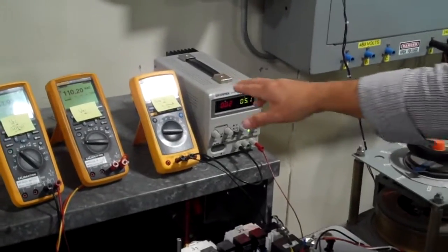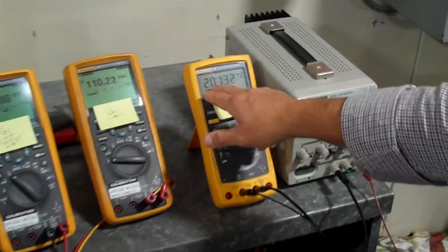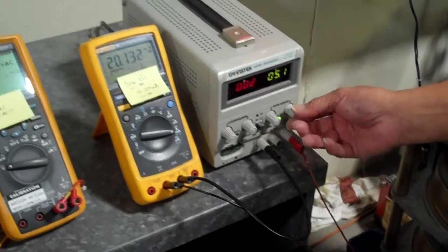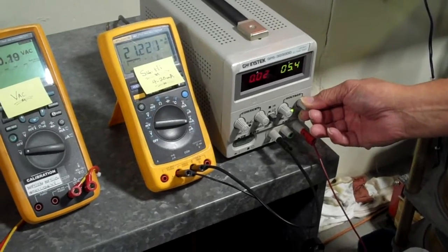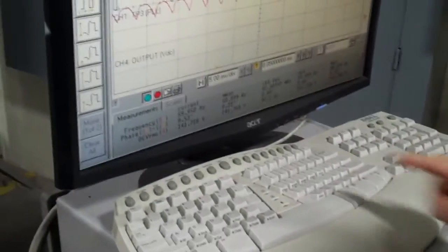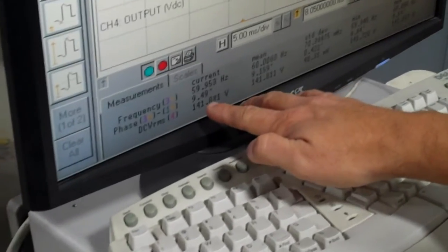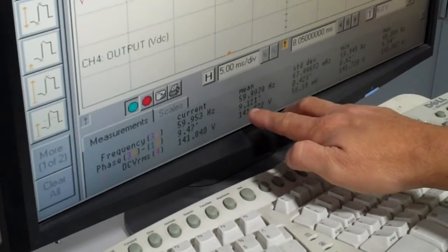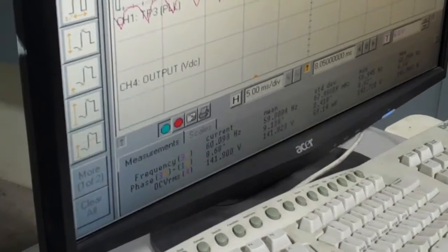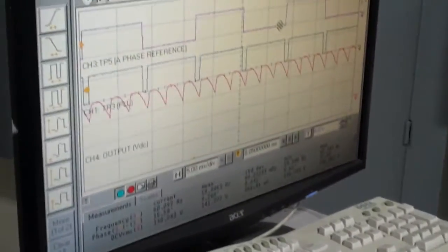So Tony, if you can slowly, by the way, and the corresponding voltage for 20 milliamps is 5 volts. Can you go a little higher, Tony? 21, that's probably good. We'll see here now that the delay angle has been further reduced to about 8.6 to 9 degrees. The average is 9 degrees. So could you slowly come down while we take a look at the screen? Okay.